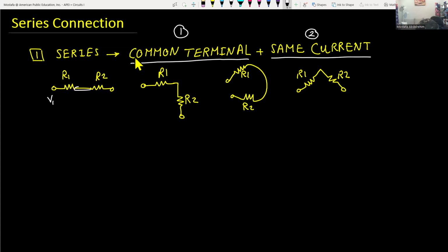Remember, guys, from the last video, we said that a wire that has nothing in an electric circuit is basically a short circuit, and a short circuit has equal voltage wherever the location on it. So the voltage here is exactly like here, and exactly like here. That's basically one node, so we're going to call this terminal V2.